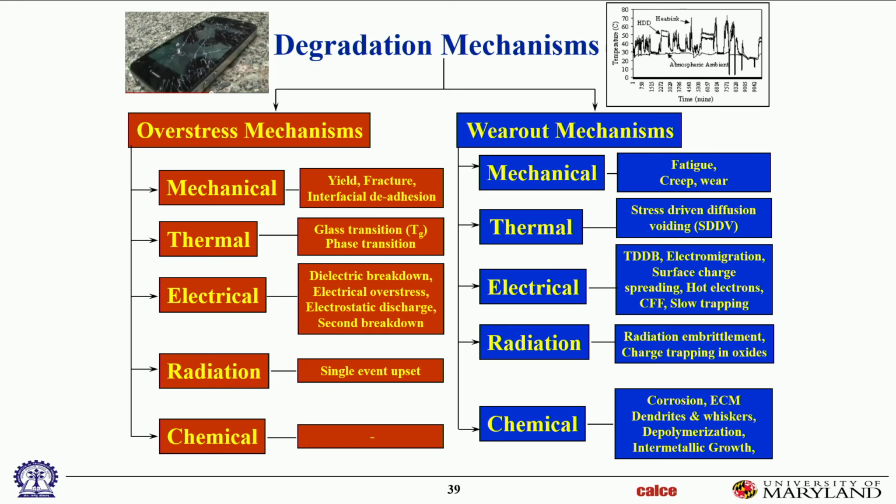So I talked about PSAs, pressure sensitive adhesives. Those sometimes will come apart. If you drop this, you may not fail the display, but the display may debond from the frame. And that's because the adhesive interfaces fail. So sometimes the failure is interfacial. So the failures may be inside a material or at the interface of two different materials.